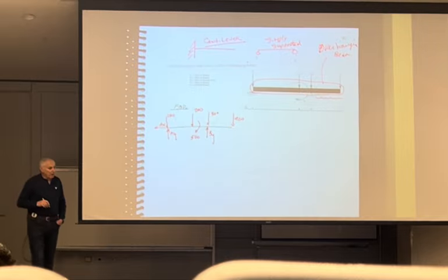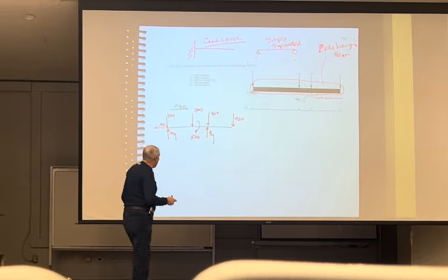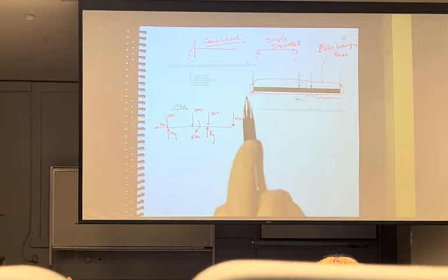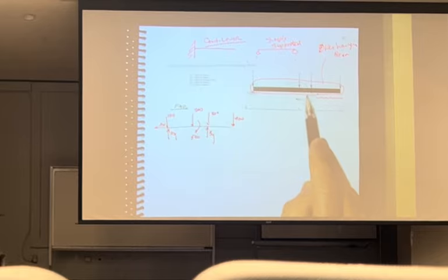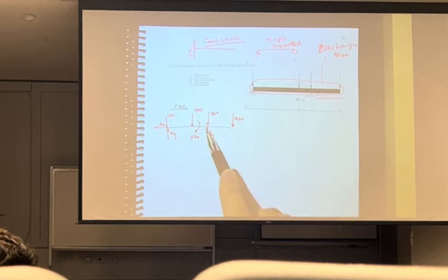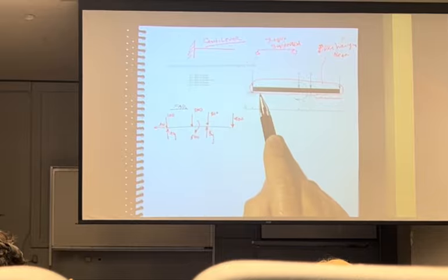That's my free body diagram. Wherever my circle touched, I got to show. I touched the pin, AX, AY. I touched the moment, got to put a moment. I touched the roller, got to put the roller. I touched this 400, got to put the 400. I touched this guy 300. I touched this guy 200, and I came back.